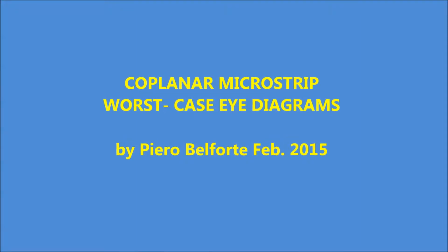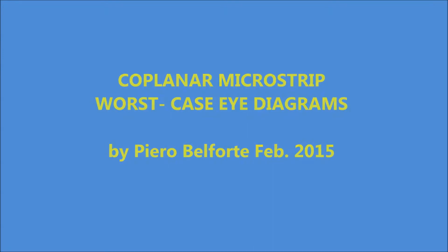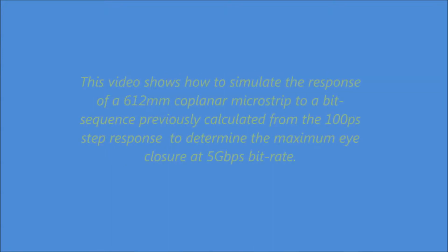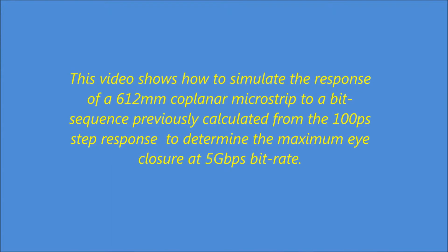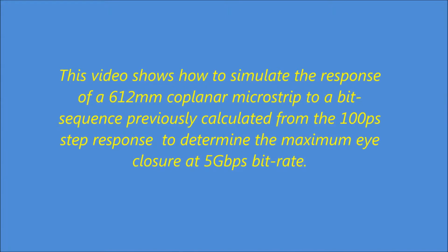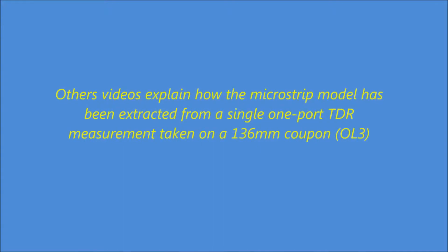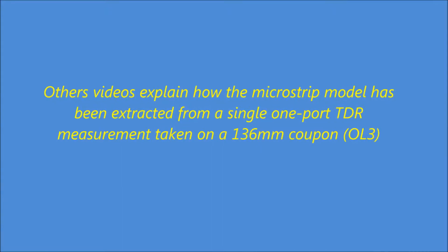This video shows how to simulate the response of a 612 mm long coplanar microstrip to a bit sequence previously calculated from the 100 picosecond step response to determine the maximum closure of the eye diagram at 5 gigabit per second bitrate.